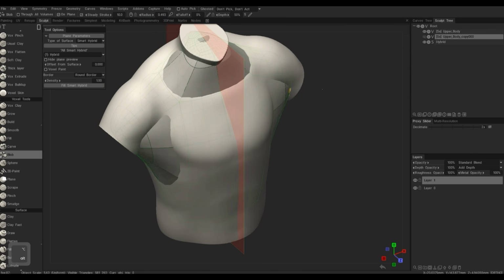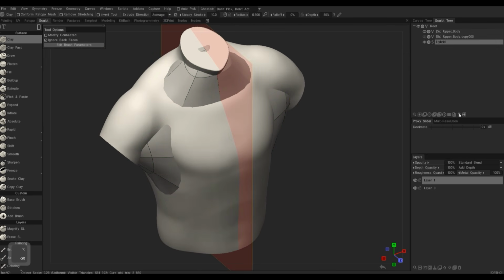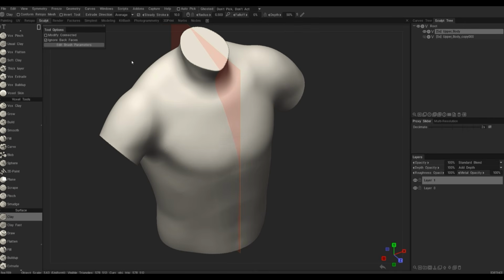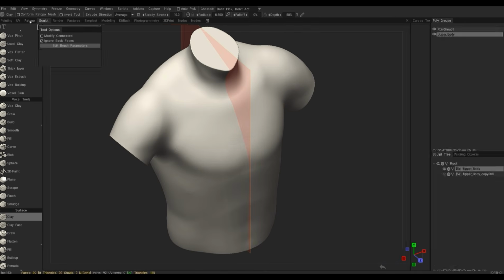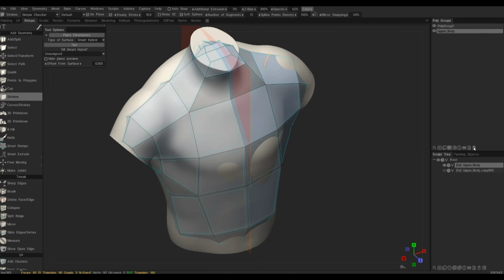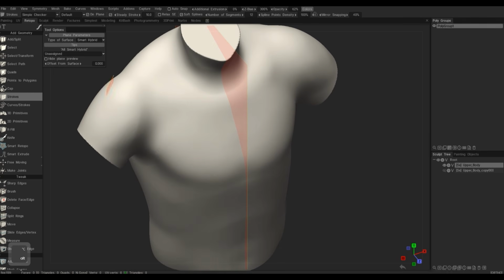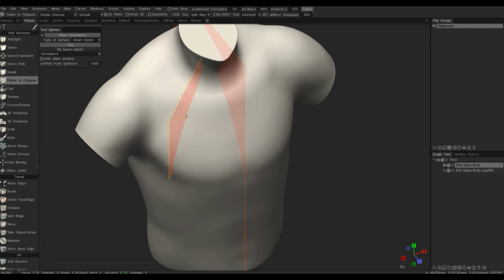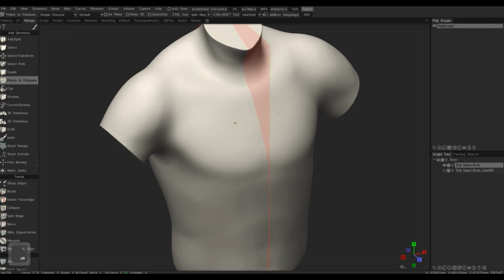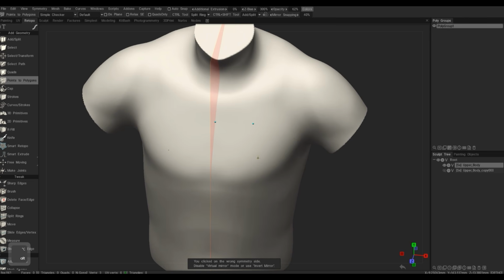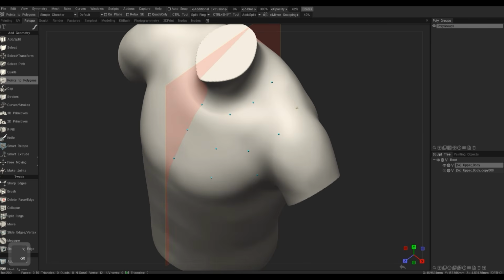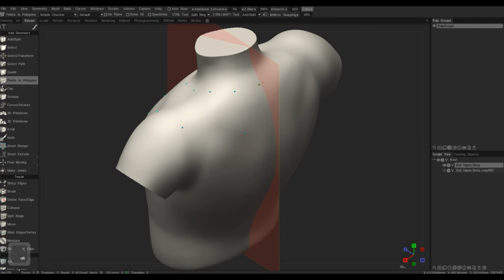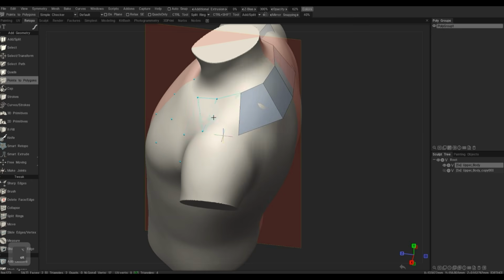So let me create a new one and I will delete this existing one. I'll go into the Retopo room, delete this upper body, and start doing the Retopology to prepare my surface. For that, I will use points to polygons and I don't need the on-plane here. For points to polygons, I will be just clicking and placing the points, placing these quads all around it. And I press the right mouse button and create a fill of the quads.